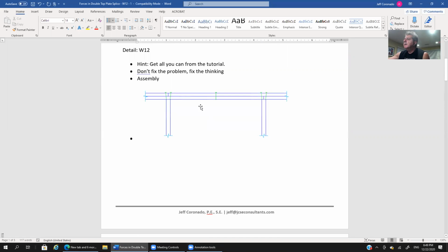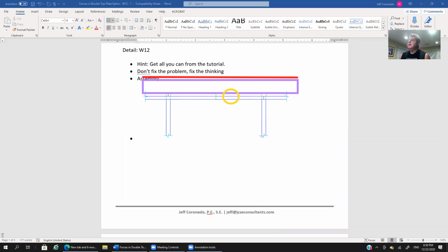Keep in mind, what we're not showing here is the actual, let's say, wood structural panel, the actual floor or roof assembly. Let's assume that this is framing here. All right, there's framing here. So the sheathing, the actual sheathing is probably right up here. Point is, this element, the double top plate, is in close proximity to that wood structural panel, to the sheathing, to the diaphragm, right?